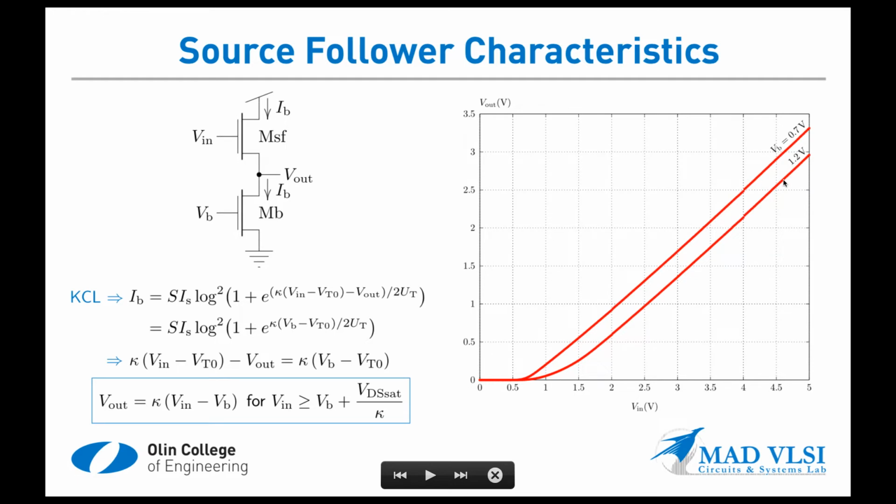And you can see that the circuit behaves in pretty much the same way. And if we extrapolate this back down to where it intercepts, it's arguably about 1.2 volts, which is the bias voltage. You can see that one of the key differences here is that for the strong inversion curve, the approach to saturation is kind of stretched out some, and so that's why this is a bit rounder here than this one is.